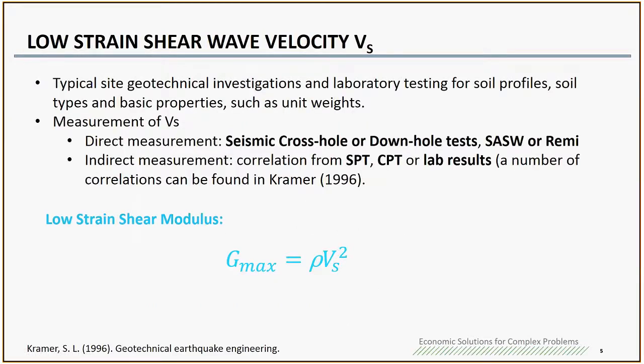So, before you measure the low strain shear wave velocity Vs, you also need to do the typical site geotechnical investigation and lab testing to determine the soil type. You still need to do the index property testing and also some basic properties like the unit weight. If you have a clay, you need to know what the cohesion is for the clay, either clay or sand.